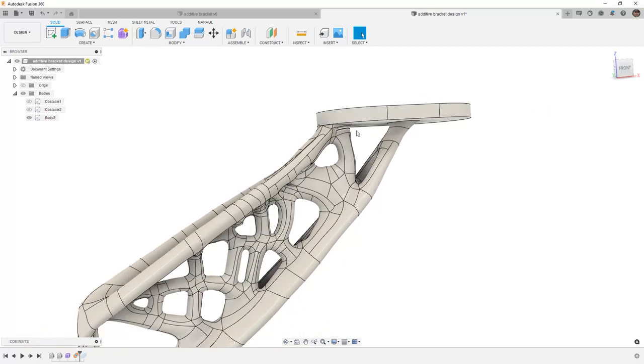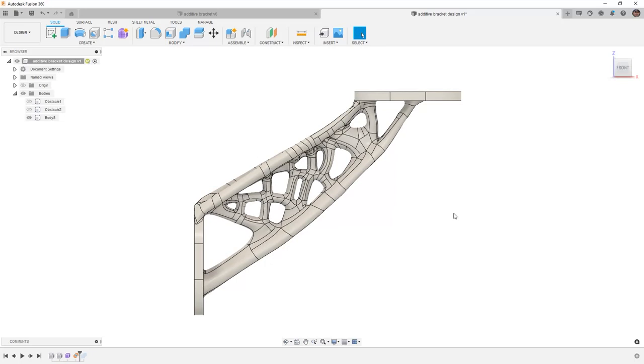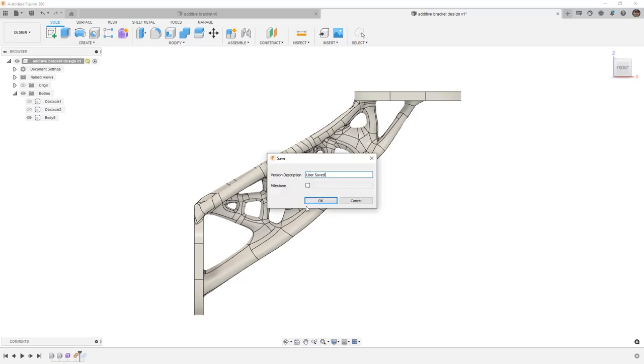bump on the backside. So as we look at this design, this is a pretty common result that we would get from generative design. It's going to have these sort of stems or spokes and some openings, and these are typical of what you would want to play around with and modify and smooth out. So I strongly urge you to play around with this model in the Forms toolset to make sure that you are comfortable with making these modifications and you explore what it can do on a generative design. This can be really helpful for post-processing your designs and getting them to that final position where you're ready to manufacture them. For this example, however, let's go ahead and save it before moving on.